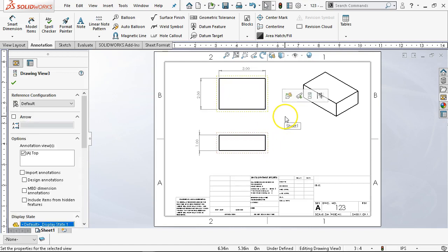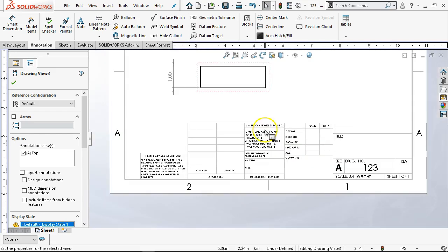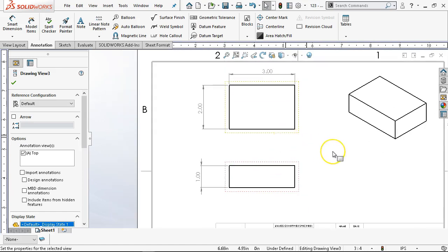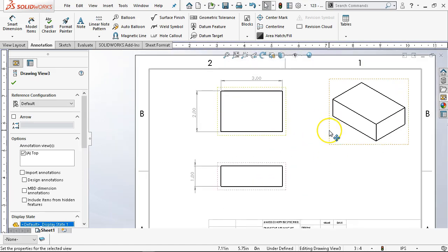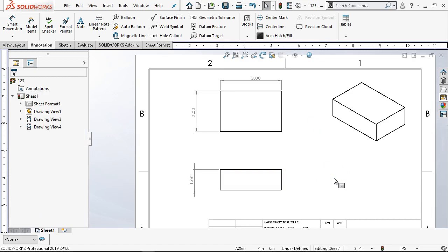Okay. So this is driving the standard tolerances, you know, plus or minus. Oh, well, this is the default, so there's a bunch of zeros in there. All right, so we probably would want to modify those in our normal sheet. So if this satisfies the criteria, I don't really need to take it any further. The plus or minus 5 that we would build into that table is going to satisfy our